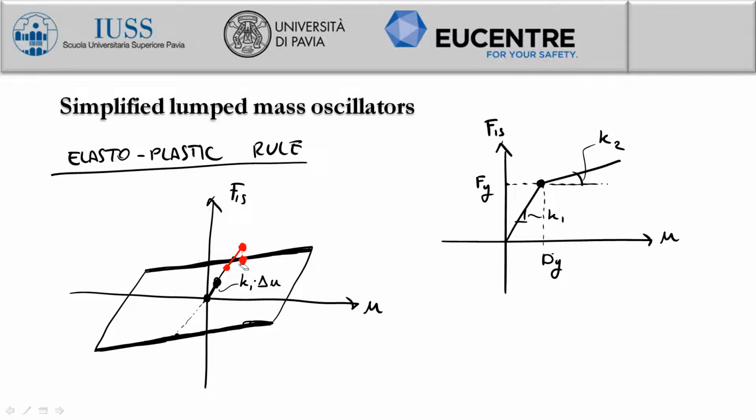So I will compute the force response according to the proper yielding line. You just compute a trial for the force by adding this force increment, and then you check whether you fall within these two lines. That is the force, correct. Otherwise, you have to compute the proper post-yielding force according to one of these two lines.